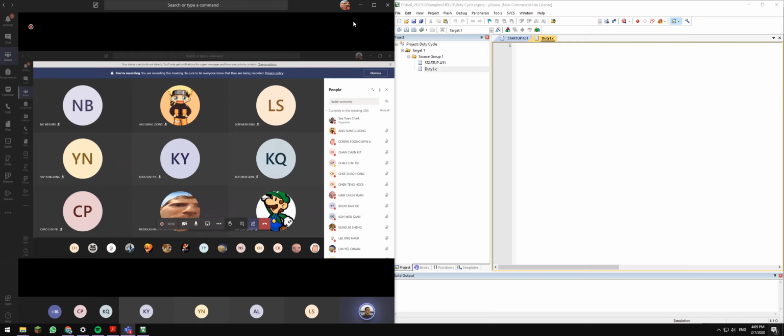So we identify what the inputs and outputs are, and if you're using a timer, what kind of special function registers are involved, and if you're using interrupt, what types of special function registers are involved. Let's say we are using PIC18 or PIC24. So the datasheet is your best friend at that moment to identify what instructions and special function registers are involved. Okay, so then we do a bit of discussion.